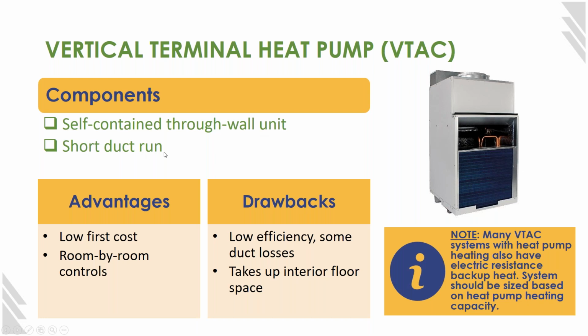But these do actually have a very short duct run. So what you'll see often is these are in a closet where you have the air intake here, this duct goes up, and then it dumps into the room at the top of the closet. So they're technically not entirely ductless, but it's an extremely short duct run. So advantages of these, they are also quite low first cost, and you can have room by room controls. There's also potential in low load scenarios where you could duct this to one room and another one, and so they have that built into them. So technically not ductless, but it's not a fully ducted fan coil like we usually think of.